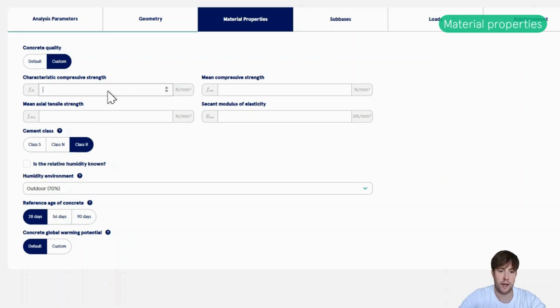So let's just say that I write 8 here. Then the remaining parameters will be suggested based on the equations from Eurocode. So I can just tap, and then I tap again, 16, 1.2, 24, 25.3. So you can tap through the remaining material properties.